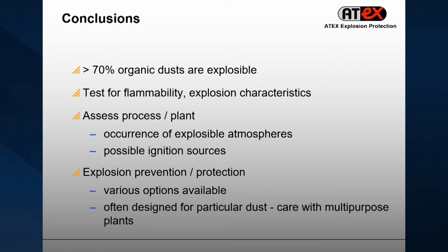That means how easily the dust is ignitable, and you also have to measure the explosion characteristics, which means what kind of consequence an explosion can have, how high the Pmax is, and how fast the pressure rise is, because that defines how quickly you have to go with your suppression or your venting system.